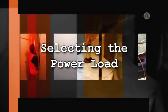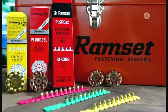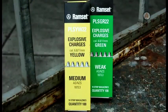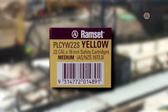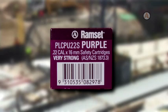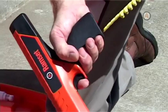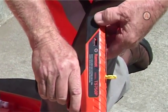Selecting the power load. Of great importance to the successful setting of fasteners is selection of the correct power load. Each power load contains a specific type and quantity of explosive that relates to the relative strength of the power load. The relative strength of the power load is clearly marked with a color coding and a description on the box, along with a list of tools for which the power loads are suitable. To determine the most appropriate power load for a fixing, begin by using the weakest strength and minimum power setting. Then, gradually increase power and load strength to obtain the optimum fixing.